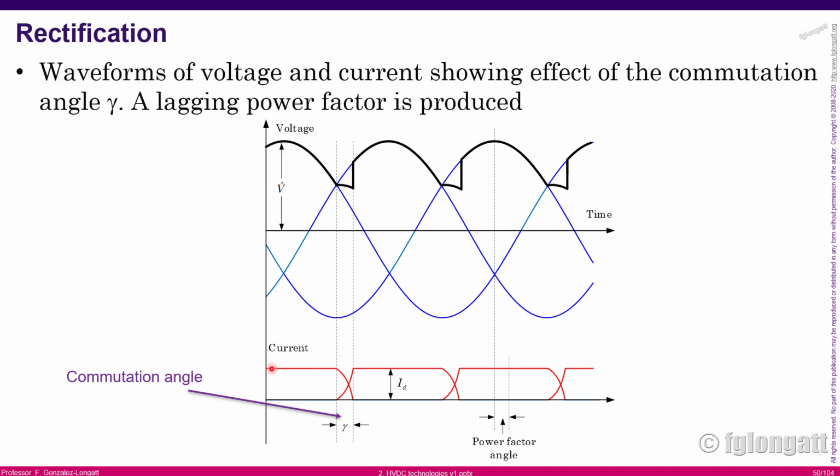And then we have the commutation process, okay? When the device is closed, there are some currents, and then when the device opens, the current tries to go to zero, but that is the moment that the other device is coming in, and we try to keep the current constant with those pulses over here. One pulse for phase A, one for phase B, and one for phase C, okay? At the end, what is important to understand is that the rectification signal is coming from the combination of the voltage and current signals across the commutation device, okay?